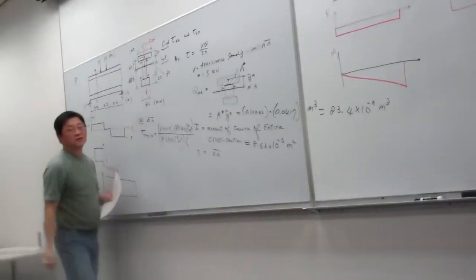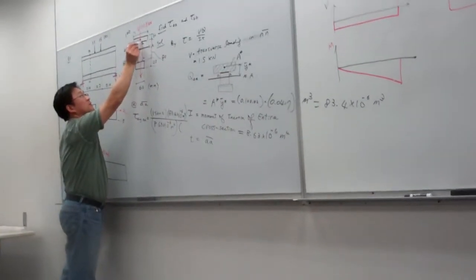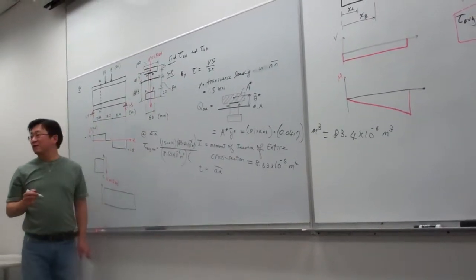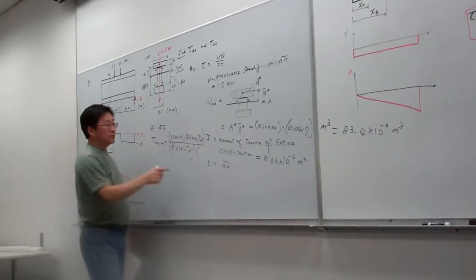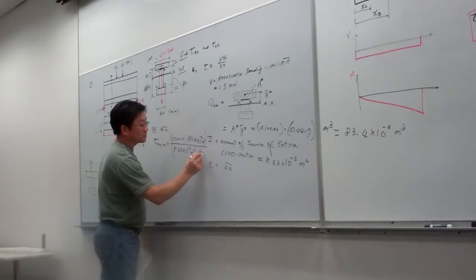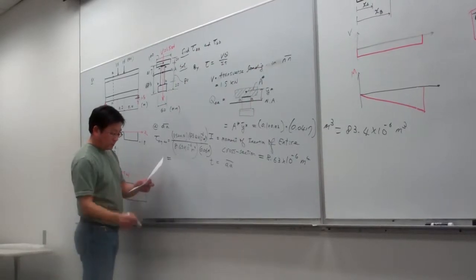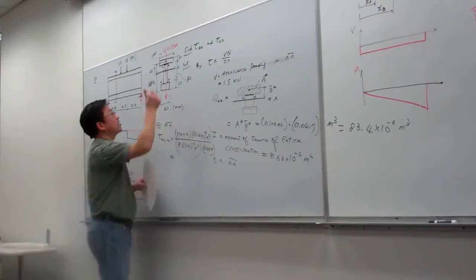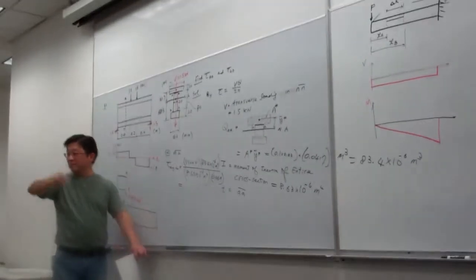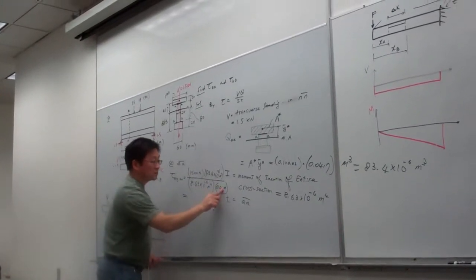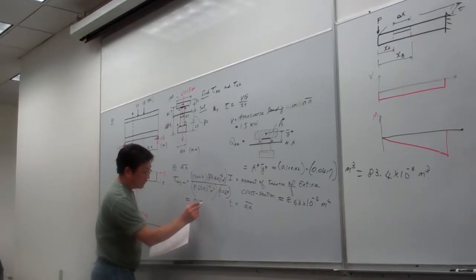And T, what is T? T is the thickness at the level here. So here. For the I-beam, once we cut, they only cut that one. So that one is 0.06 meters. Okay, so this calculation, I didn't give you, this one is 20 millimeters. The width of the flange is 20, so this is 0.2. So that one will be 725 kPa.